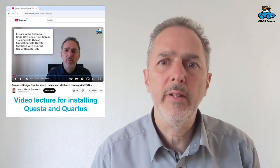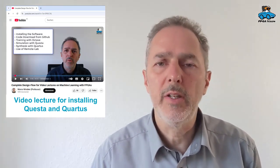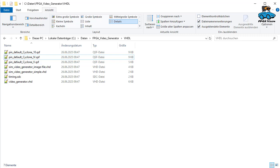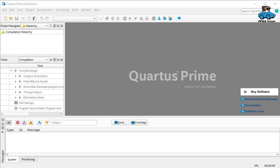And if you need help in setting up the software, there is a lecture that explains the installation and use of the design flow. The required files are in the subdirectory VHDL. You extract them to a working directory, and then you can choose between different FPGAs. We choose the Cyclone 4. And in the constraints file, you find the device that's available in the remote lab. Then you set up a project in the Quartus design software.